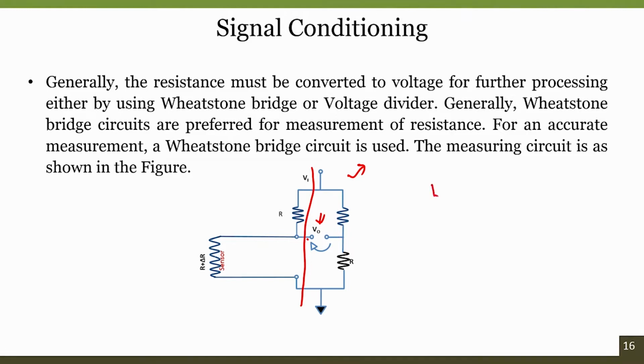What I mean is, imagine the previous circuit we had, at 10 volts, with R1 at 1K, or this is also the R1 base resistance. The output we measure is with respect to the ground. If both resistances are the same, then it is Vin by 2, which is 5 volts. This is a resistive divider, whereas the Wheatstone's bridge uses two pairs of resistive divider networks.